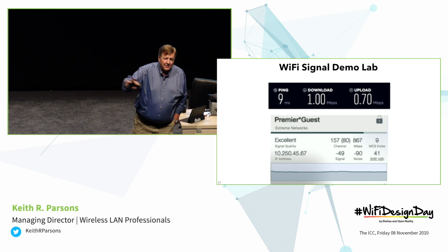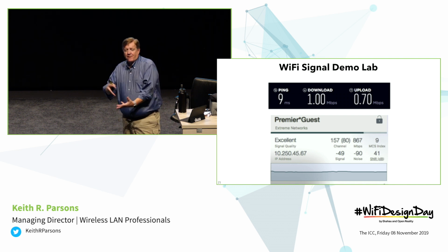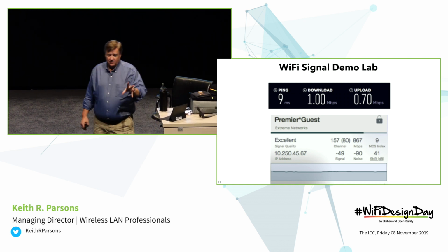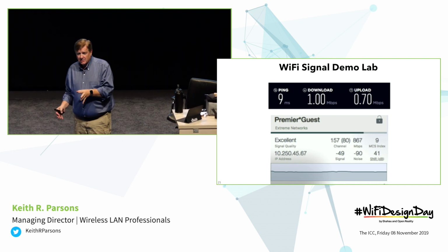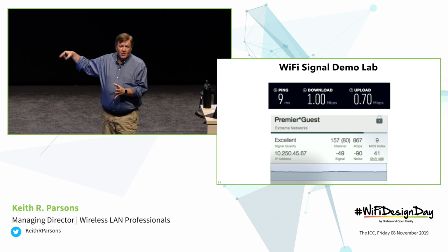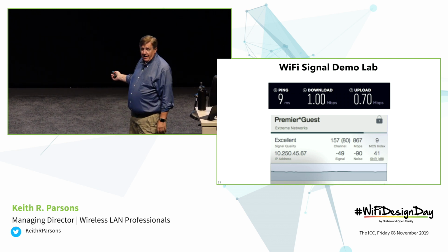And the beauty of the whole MCS issue is it self-announces. It self-says, I'm doing diagnostic frame by frame. I tried 256 QAM, it didn't work. I tried 64 QAM, it didn't work. I'm now at 16 QAM, and it's working. What you know is it tried and failed, so I have an RF issue. This one, I don't have an RF issue. I have a backhaul issue.